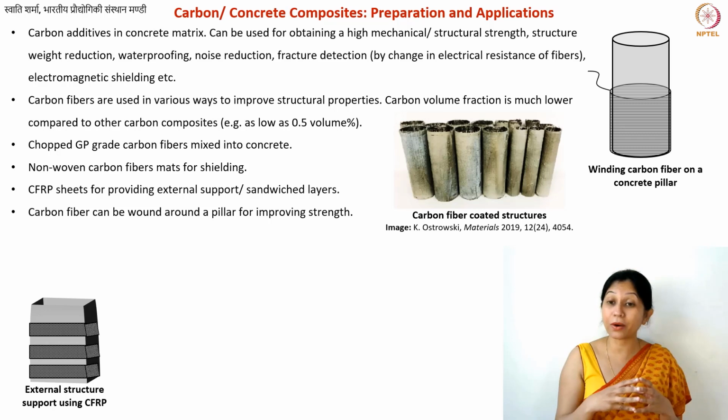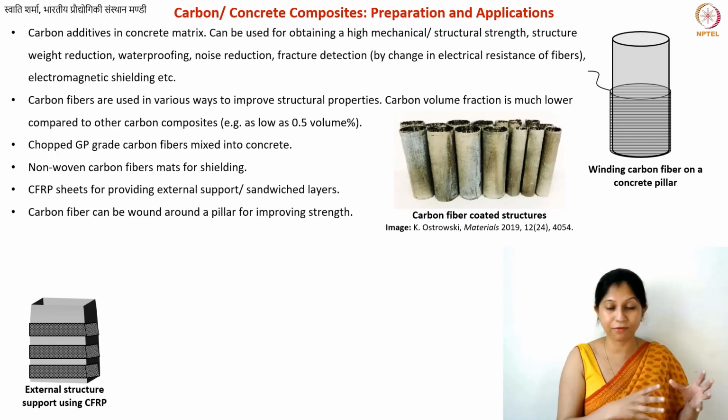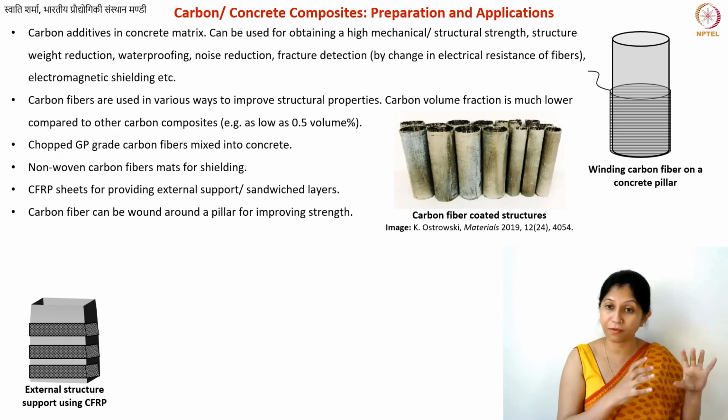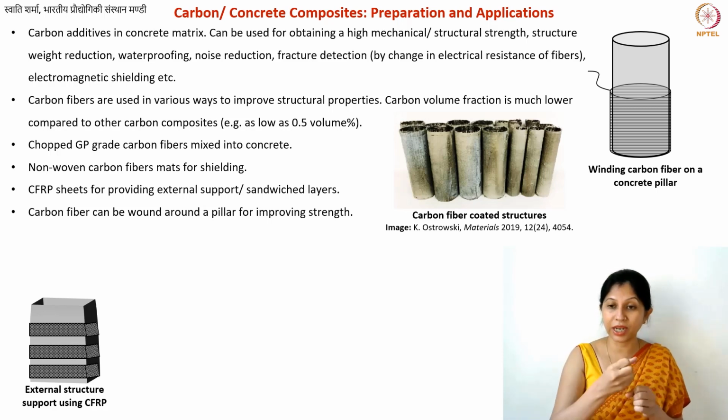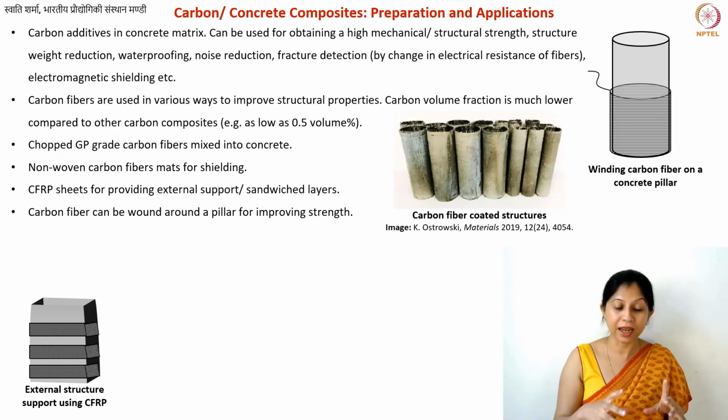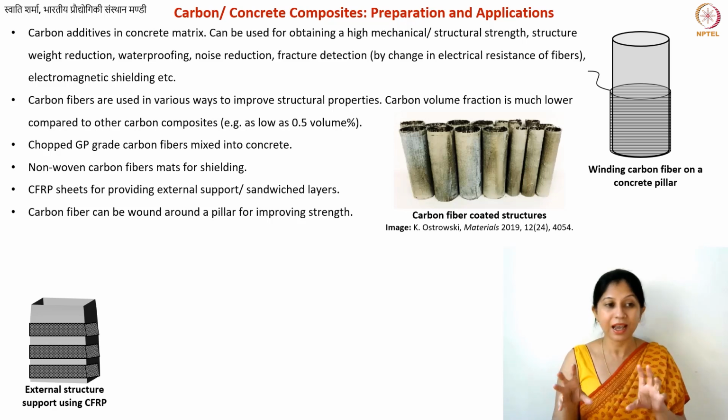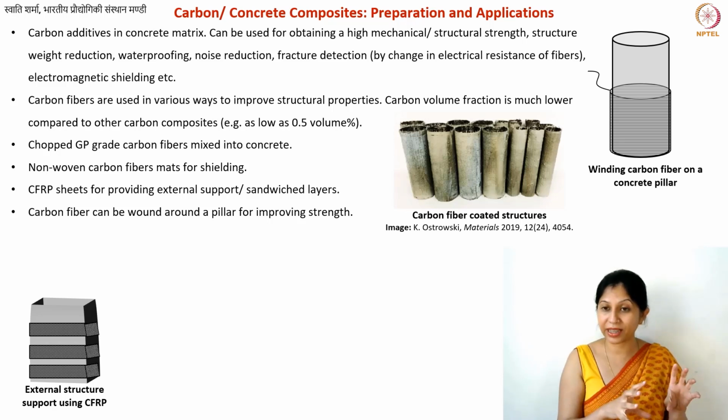These are probably going to be thick ropes. So there you have to do, remember from our mechanical property testing lecture, carbon fiber mechanical property testing. So there you need to have a good tensile strength in these fibers. Again, modulus may not be so important. Rather, the ultimate tensile strength is more important, and you will most likely choose PAN derived or isotropic pitch